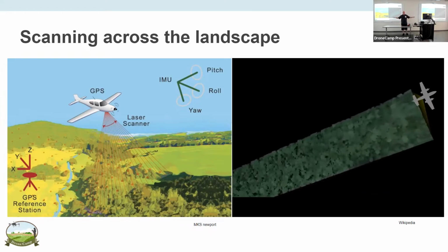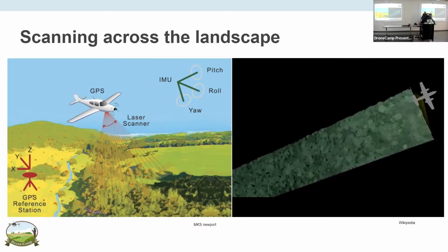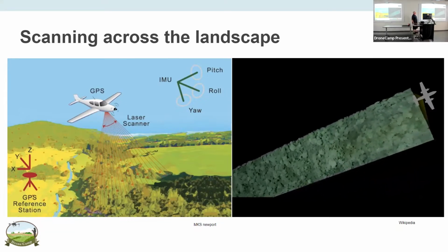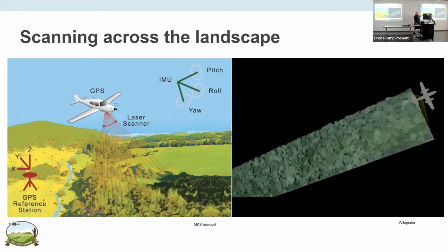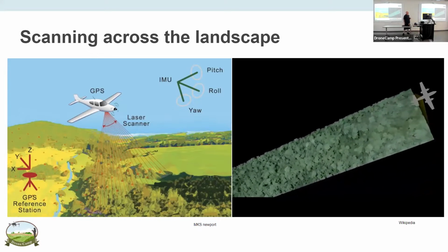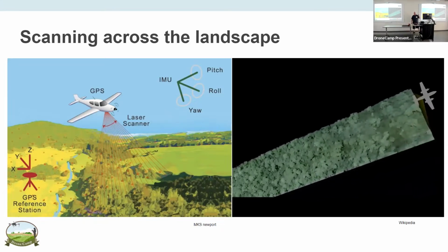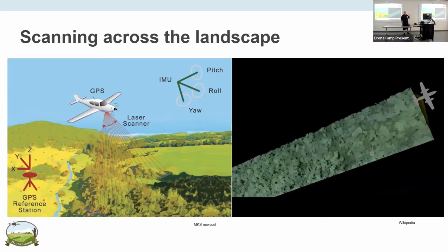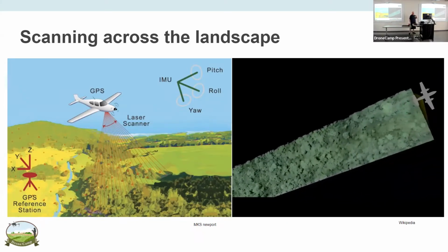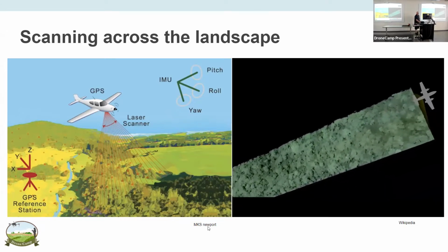And so we need to know the attitude of the aircraft. That is its pitch, roll, and yaw. You know all those names from talking about other uncrewed aircraft, as well as its position in XY space and some other factors. We need to know all those very, very quickly, like 200 hertz. We need to know it 200 times a second, and to very, very small hundredths of degrees. And those systems are kind of expensive.